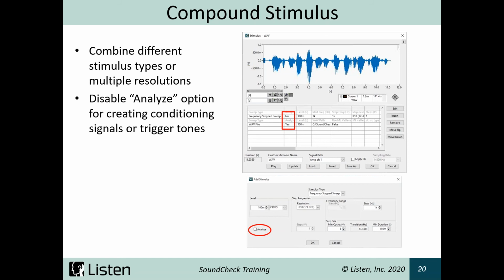So we could put in just some frequencies at the beginning, maybe a quick burst of pink noise just to wake up the device. Or if we're doing open loop testing, open loop testing often requires a solid sine wave to be able to lock on to do resampling and frequency shifting to make sure that the clocks are aligned between the two devices under test.